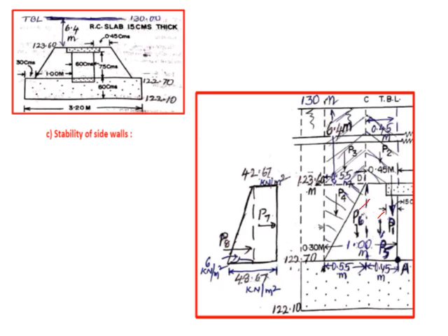So now we have to calculate what is the earth pressure. So the intensity of earth pressure is Ka gamma into H. So what is H here, from here to here, which is 6.4 meters. What is Ka? 1 minus sin phi by 1 plus sin phi, that is 1 minus sin 30 by 1 plus sin 30, which comes to 1/3. So 1/3 into 6.4 into 20 gives 42.67.